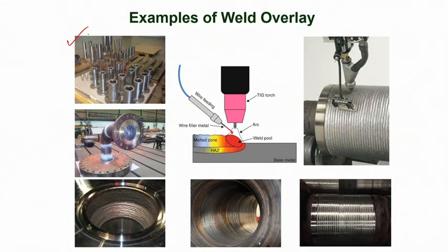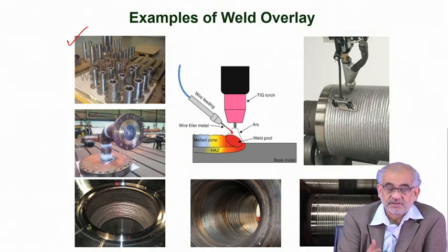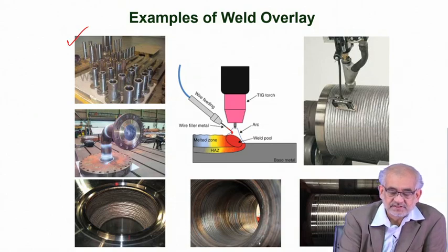This is very, very common because when they conduct fluid carrying slurry or certain other kinds of solid particles having very high hardness, they can cause damage inside or at the tip, and they need to be restored, otherwise there will be a mismatch or leakage and so on. Particularly in a situation where you have such a bent tube carrying say petroleum or slurry or say coal in coal washery or in other places, the inside of the tube gets immensely damaged, and you need to restore them by using certain process by which you can create a beam